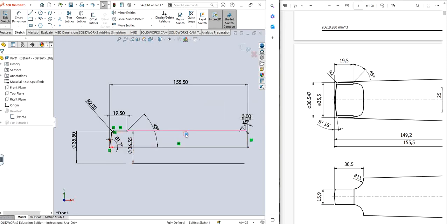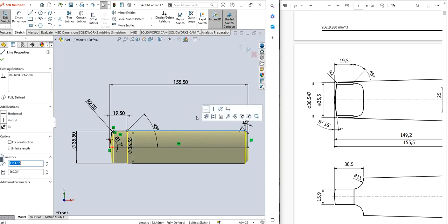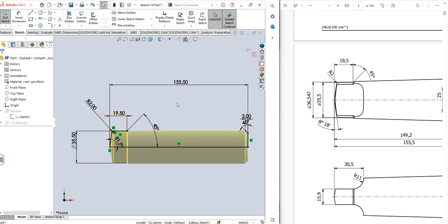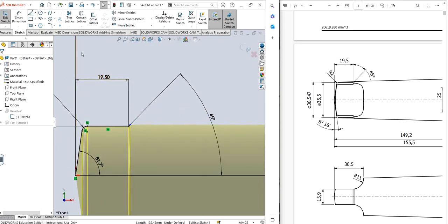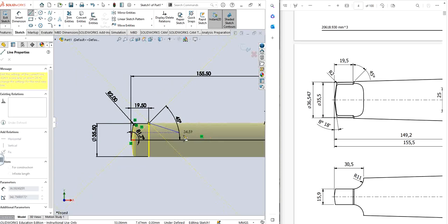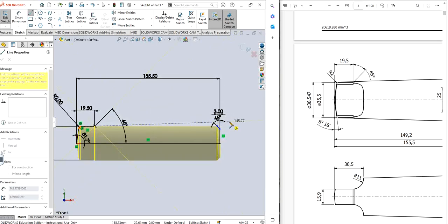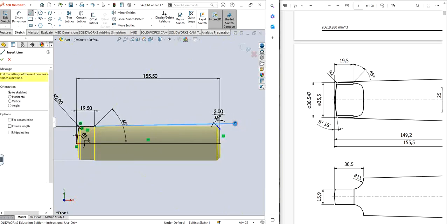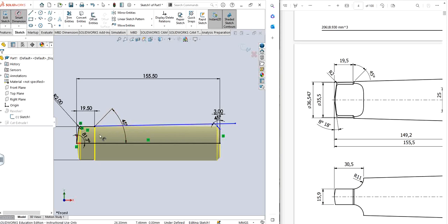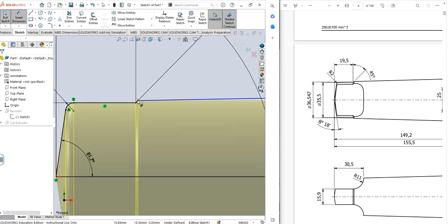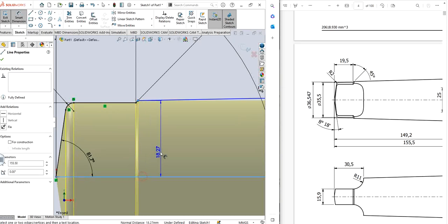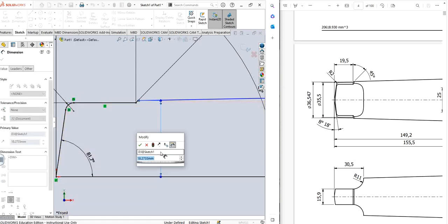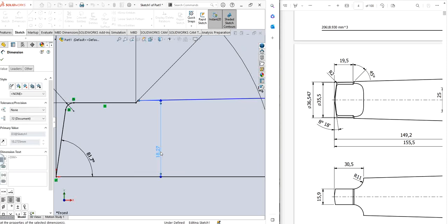This constraint, I'm going to delete it. This is not horizontal at all. I'm going to delete this, click OK, because we have two different diameters, as I just recently observed. I'm just going to zoom in and make something at an angle. Similarly, I'm going to dimension this particular side here till here. It's going to be 36.547 divided by 2 right here.